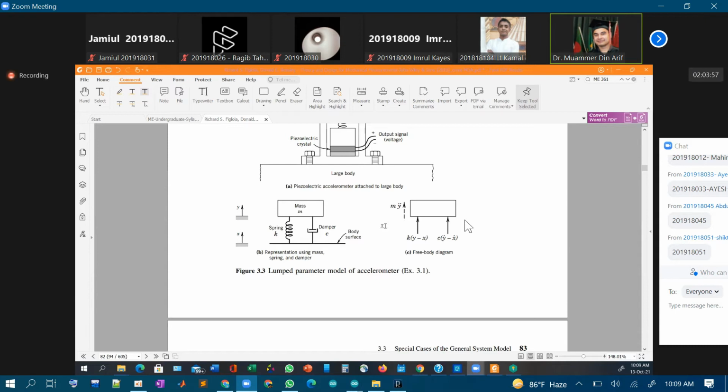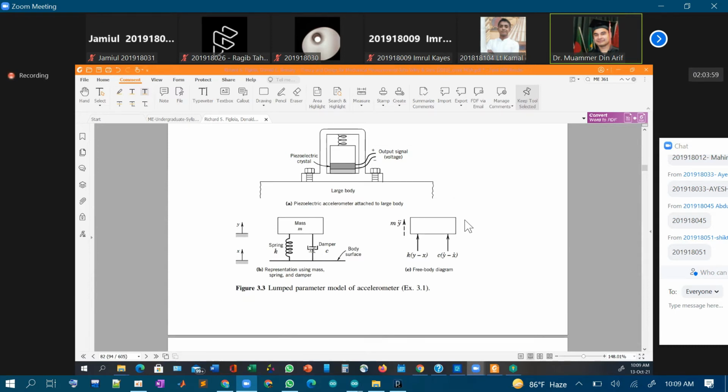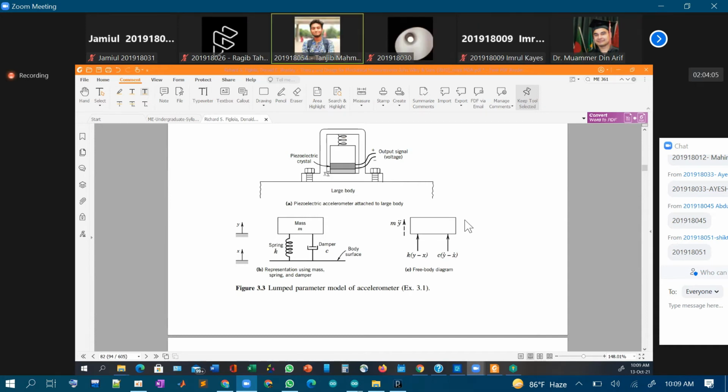So obviously, vibration measuring equipment will also have dampers inside. In this case, the air itself is acting as a damper. You could have an oil filled damper. Now why is an air filled damper used here? It is used because if you have too much vibration, you might actually break the piezoelectric. As we saw, a tiny damper, a piece of glass with a simple graphite piston, can actually slow down the fall of a 2 kg mass. So you can imagine dampers are very good and efficient.